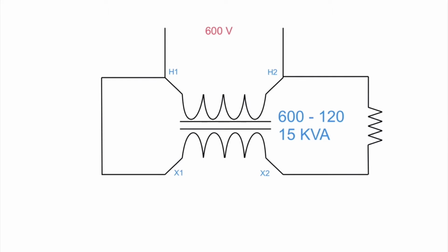In this video, we're going to be going over buck boost auto transformers. Now, an auto transformer is a transformer that shares a common winding. The difference between this type of auto transformer and a typical auto transformer is in this one, we're using a standard dual winding transformer.